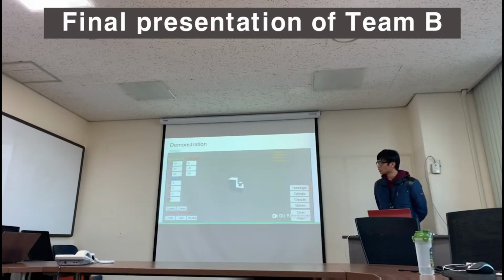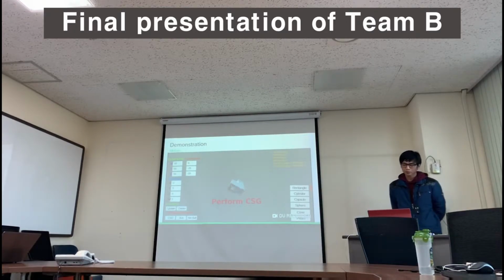And perform the CSG operation on the smaller rectangle. Reverse subtract to remove it from the solid model.